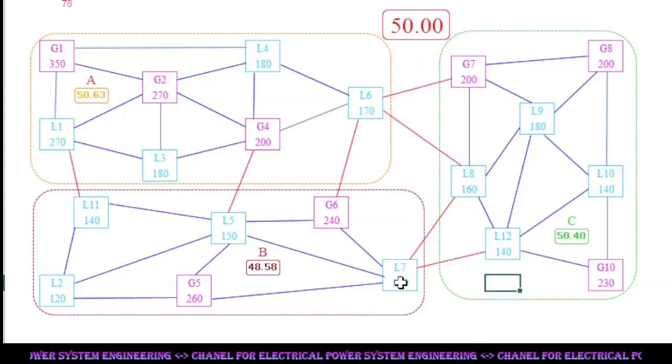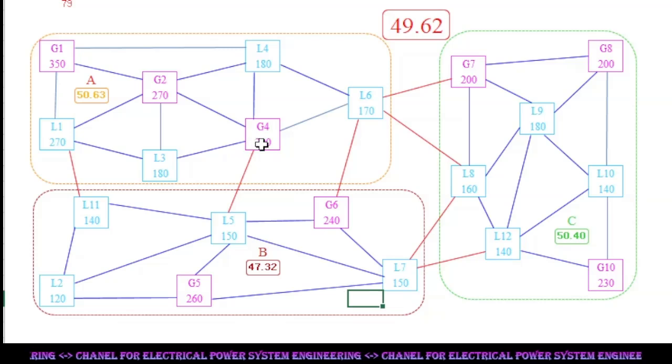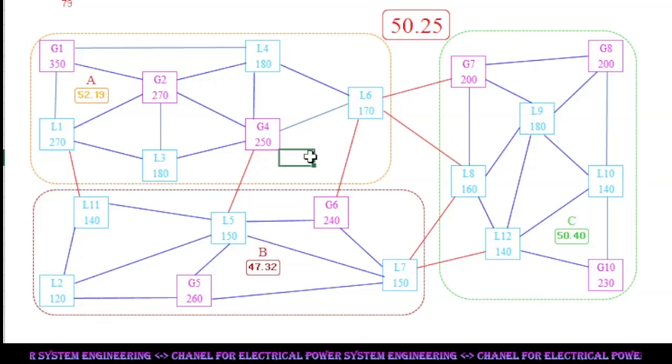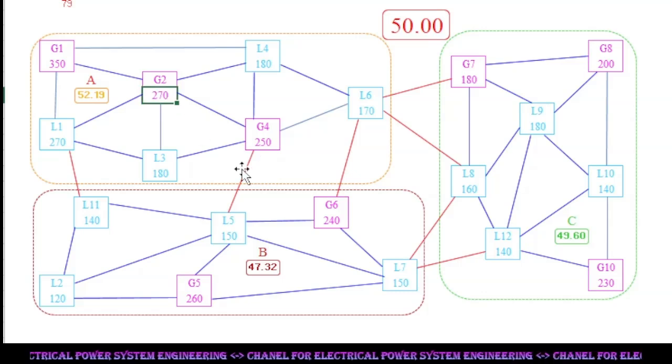Now observing the effect for variations of load and or generation anywhere in the grid. When generation reduces at any power plant in any system, the grid frequency and concerned system frequency drop. Grid frequency improves when generation is picked up at any power plant in other system. But concerned system frequency rises above normal whereas other system frequency continues as it is.